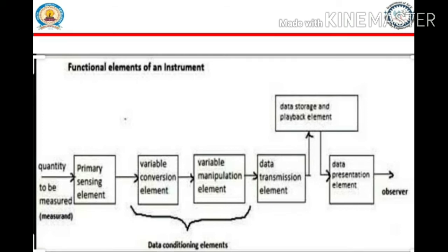So now coming to the intermediate stage. Once the electrical signal is generated by the weighing machine's input stage, in the intermediate stage this available electrical signal is processed in such a way that you will calibrate the resultant electrical signal into its equivalent mass. Before you try to calibrate and bring out the equivalent mass of the electrical signal, you need to pre-process the electrical signal.